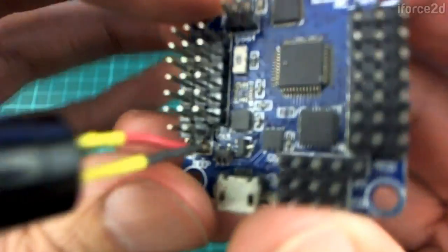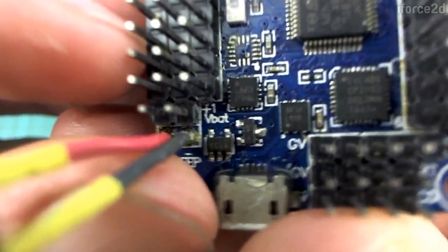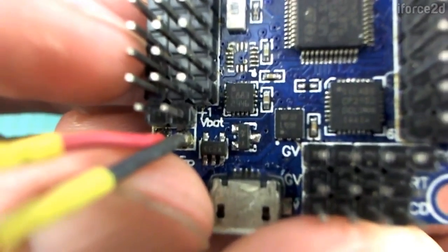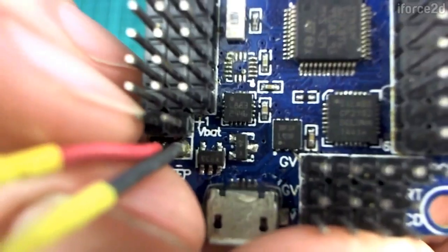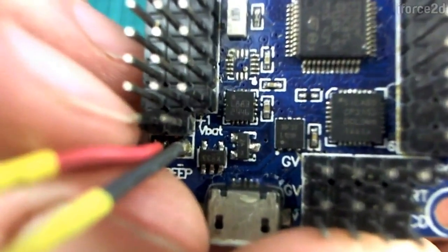The flight controller is controlling it to turn it off and on. And just above that we have something called VBAT, and this is the voltage of the battery. Battery meaning the LiPo battery, the main flight battery that's powering everything. So this could be quite a high voltage. It's going to be more than 5 volts. Could be up to 12 to 16 volts or something quite high like that.